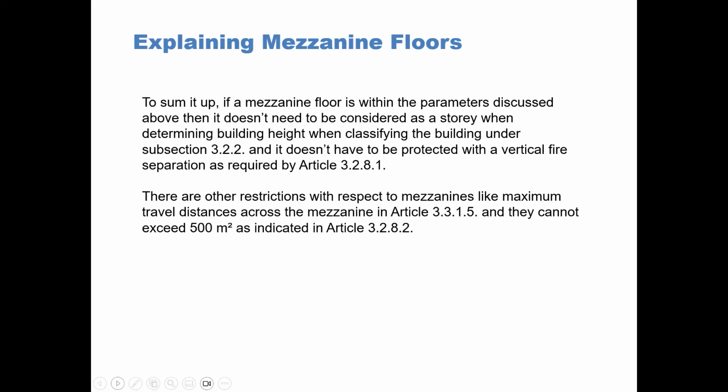To sum it up, if a mezzanine floor is within the parameters discussed above, then it doesn't need to be considered as a story when determining building height when classifying the building under Subsection 3.2.2. And it doesn't have to be protected with a vertical fire separation as required by Article 3.2.8.1. There are other restrictions with respect to mezzanines, like the maximum travel distance across the mezzanine in Article 3.3.1.5, and they cannot exceed 500 meters squared as indicated in Article 3.2.8.2.